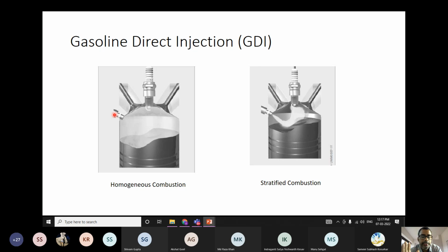The air quantity remains fixed as per the given amount of air, but the fuel injection timing and fuel injection pressure are both now variable. We need to optimize them to get the best power output, minimum emissions, and lower fuel consumption, whatever our objective is.